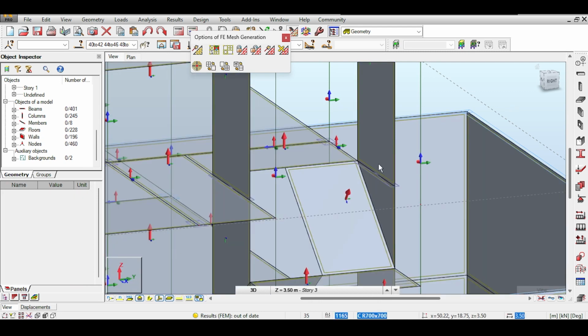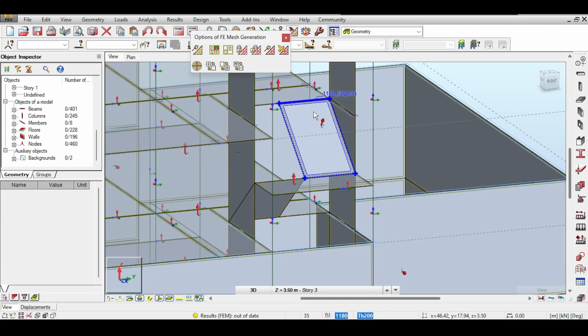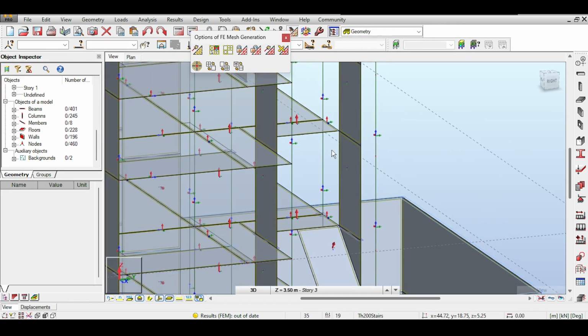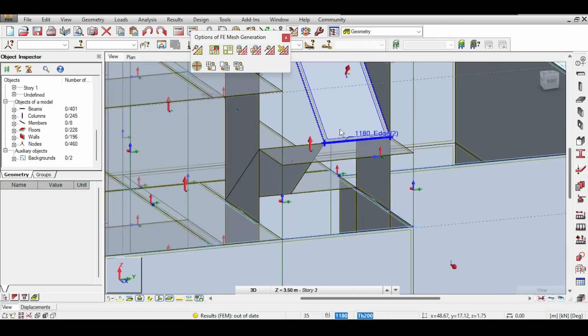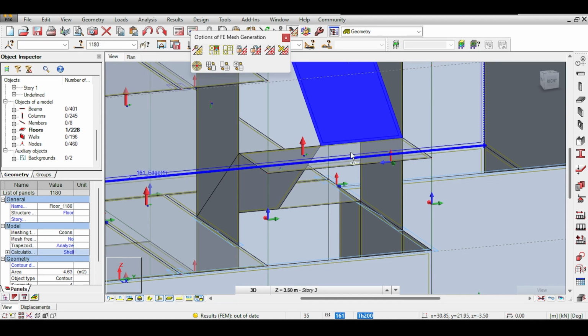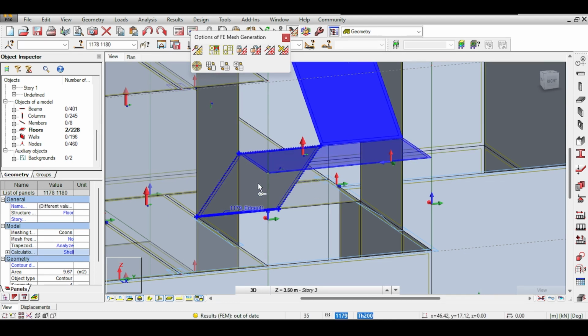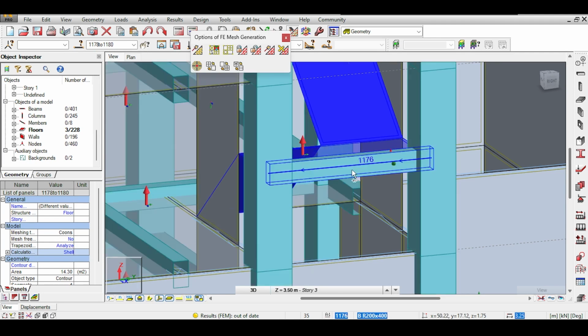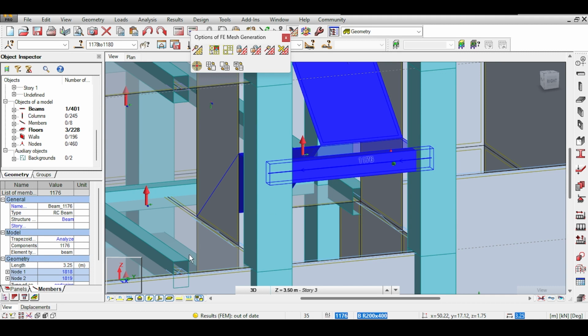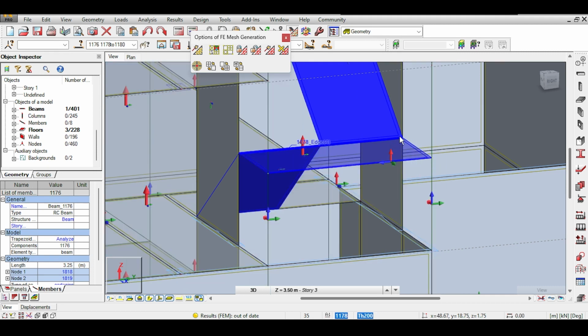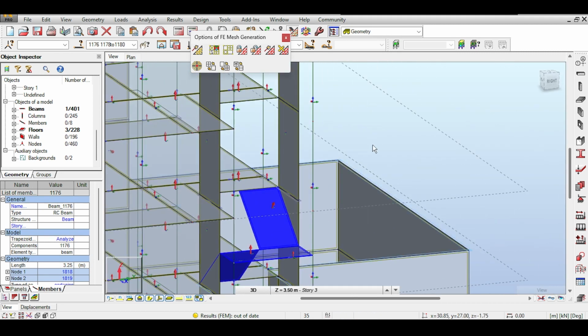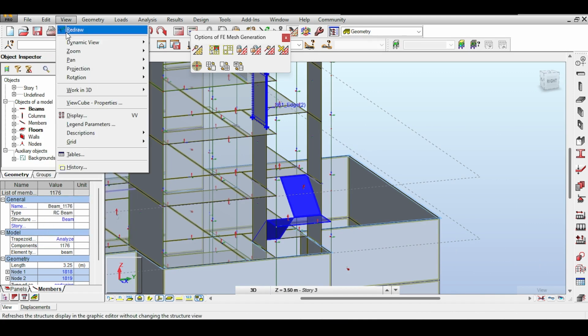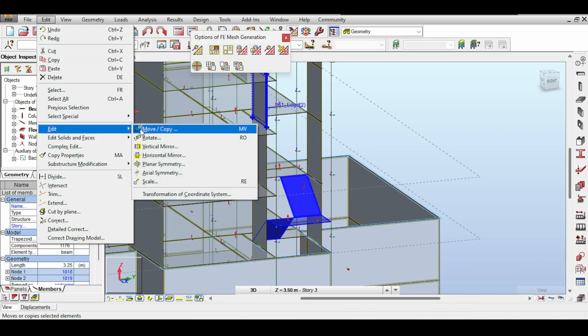Fine, fantastic. So what I will do now is I will try to edit, move, or copy it, because I think all the stories above this are 3 meters. I'm not sure. Well, there's only one way to find out. So I'll just copy this and select those 3 pieces. There is a beam I need to select, so I need to open the section first to facilitate the selection of the beam. There we go. And now I will edit, move, or copy it multiple times.